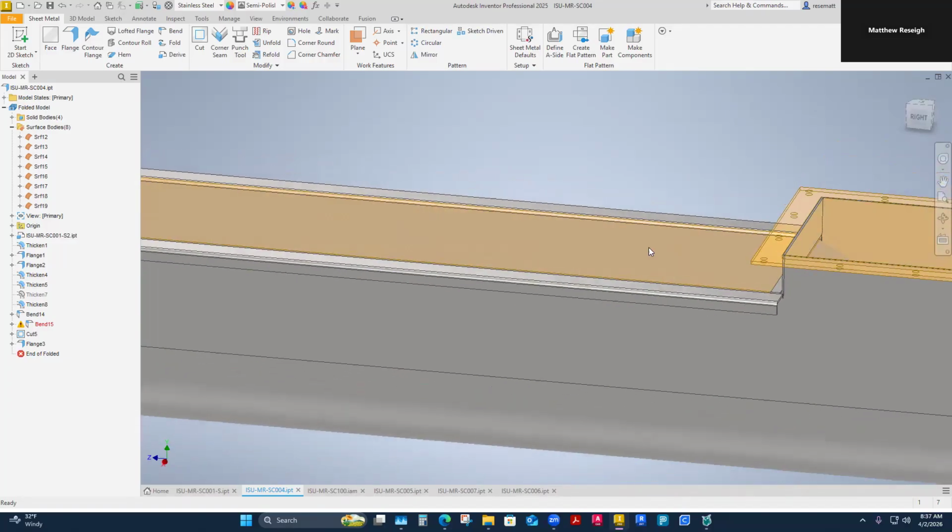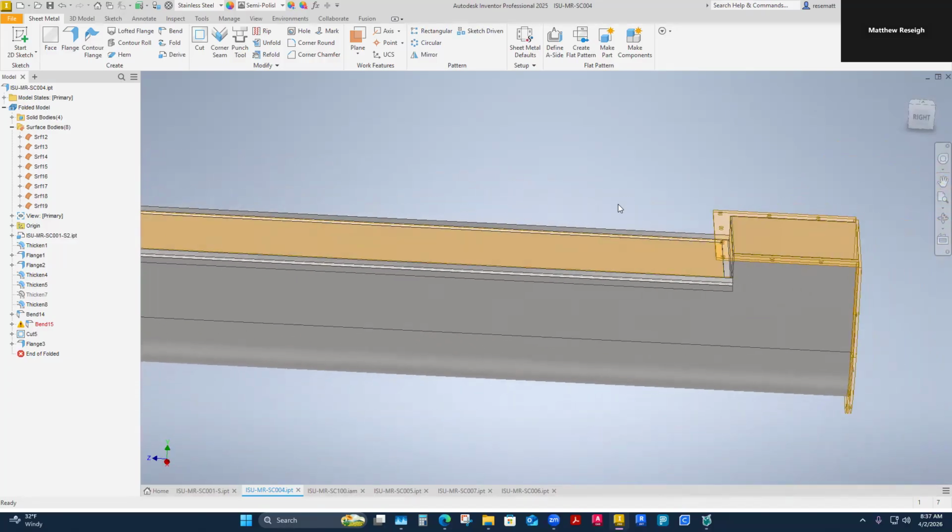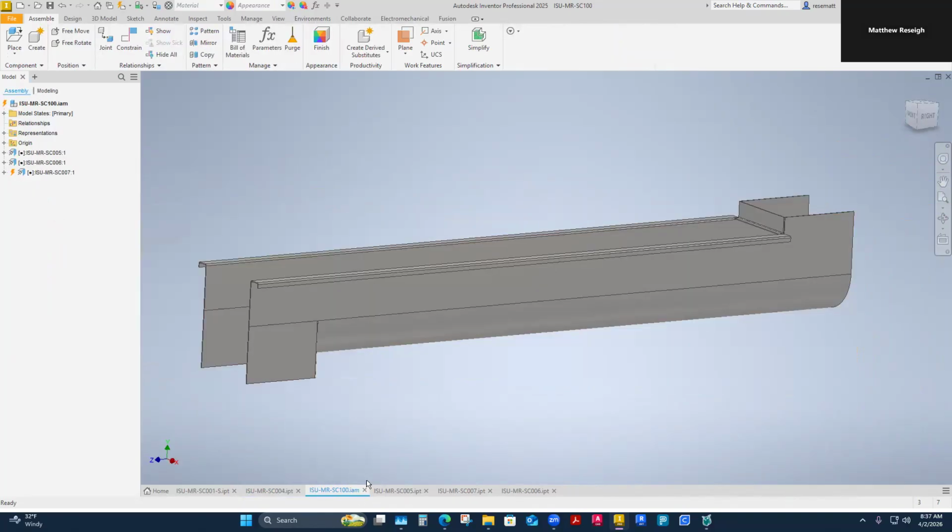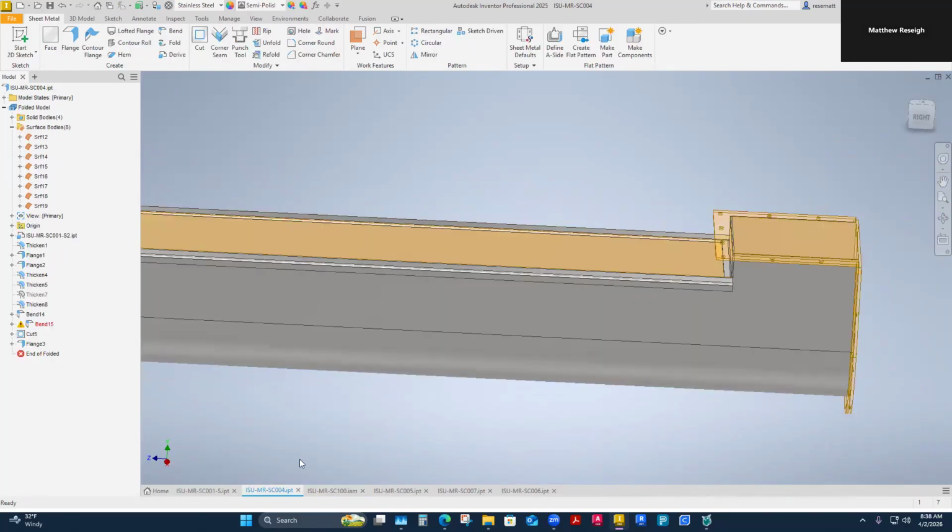When you do changes like this, I'm going to keep making some changes before I go check my other assembly, but I'll bounce over there really quick. Anytime you're making changes to that thing, you're going to get these lightning bolts going off, like they need to accept an update. We'll just update them, and the things that I've done on that other part are going to feed downstream into this part as well. If I'm making a heavy and extensive amount of changes, I sometimes go back and forth between that part a couple of times and update it so I don't crash it. If you do a major overhaul, sometimes it's helpful to do that in littler chunks and keep updating that other file.